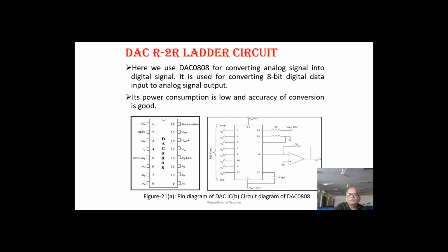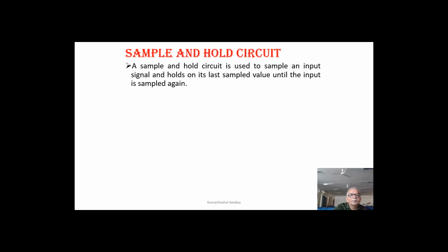So assuming 0 to 1 volt is the range, that is 0 to 1000 millivolts, you will get a step at every 4 millivolts, and therefore resolution is very good. 4 millivolts is equal to 0.4% resolution. 0.4% resolution is difficult to get in mechanical systems.